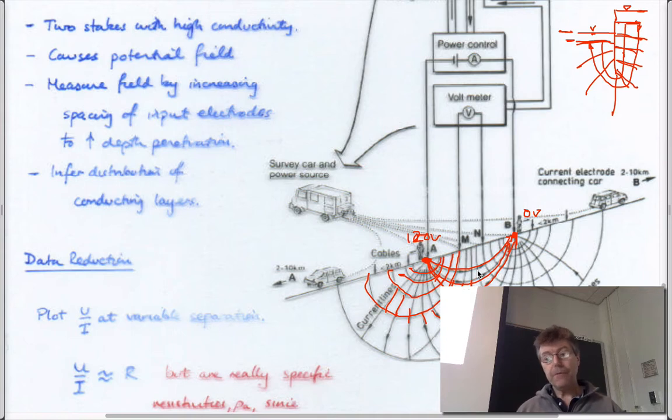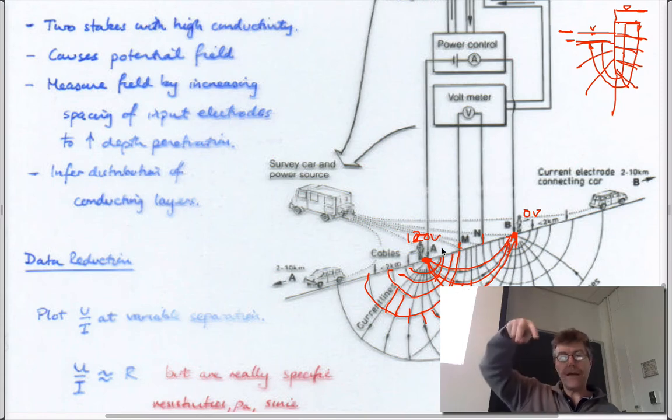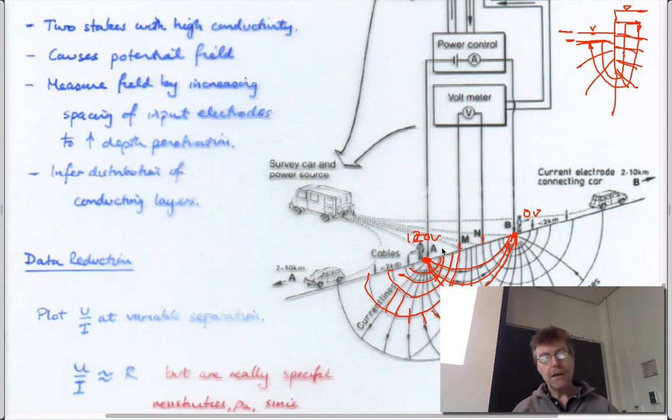And so what would happen then if you now took two other electrodes with an ohm meter or a voltmeter on them, just like you could buy in Radio Shack before they went bankrupt, put it into the ground, and you'd measure a difference in voltage here, which would be 120, 110, 100. This would be 90, 80, 70, 60, 50, something. So you'd measure 90 here, and if it's symmetric about this, I guess you would measure 30 here. And so you'd get a measurement of the potential drop across here.